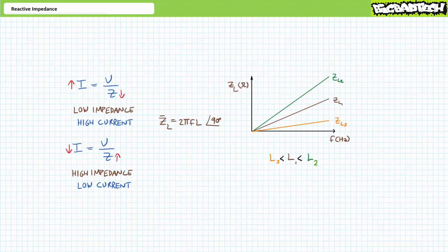Think about it. What's the steady-state impedance of an inductor in a DC circuit? After the transient storage phase ends, an inductor appears as a short circuit or 0 ohm impedance. After an inductor contains a stable magnetic field, it experiences no voltage differential. This perfectly defines a low impedance element.